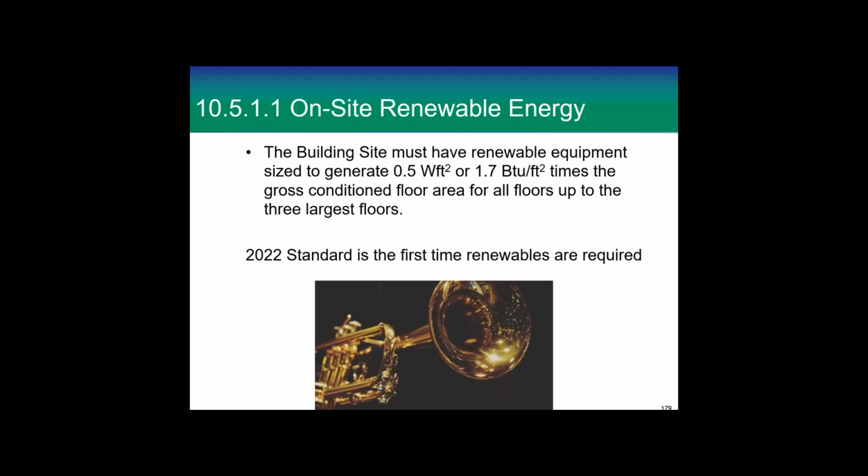On-site renewable energy. I told you before, but here it is: in 10511 is the first time we've ever required renewable equipment. It's got to be sized to generate 0.5 watts per square foot, or 1.7 BTUs if you're making hot water, times the gross conditioned floor area of all floors up to the 3 largest floors.